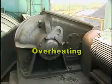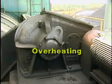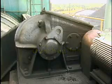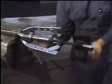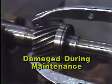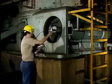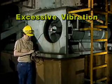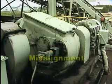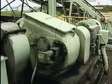For example, overheating could be caused by a buildup of dirt on a gear unit that is cooled by radiating heat to the environment. A third reason for bearing failure could be that the unit was damaged when it was first installed or during subsequent maintenance. Another cause for failure could be that the unit experiences excessive vibration when it operates. A gear unit being out of alignment or position is another common cause of bearing failure because it places an additional load on the bearings.